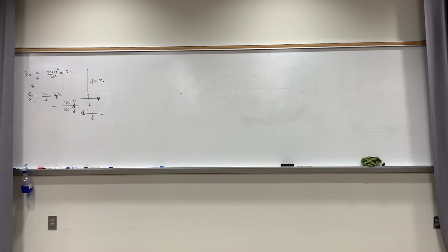But let not your heart be troubled. What he meant to say is that 1.64 would be the gain if it was a half wave, right? But this is going to be a little shorter than a half wave, and it's in that gray area. Honestly, if you're below a half wavelength, default to the equations for a short dipole, a standard rule of thumb. 1/3 is quite a bit less than a half. It's not just slightly less than a half. At 1/3 of a wavelength, you can do this and you're going to get a pretty good answer.